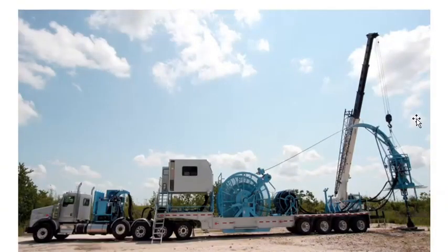Now see the working of the injector head via this picture. Here we can see that the coil tubing pipe is being fed into this injector head from this coil tubing reel and over this gooseneck or guide arc, and then this coil tubing pipe is injected into the wellbore with the help of this injector head. As I explained at the start of this video, the injector head is one of the 6 major components, and these 6 major components are shown over here.